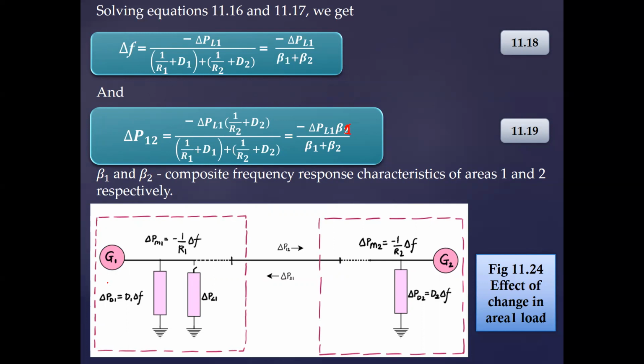You have dynamically varying load disturbances taking place every minute and so on. So this supplementary control will be applied on a selected generator. This is one part, very clear. But that selected generator can be the economical generator, and that economical generator you get after solving the optimal power flow.